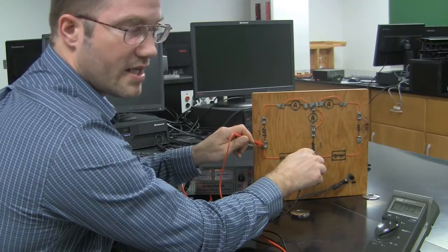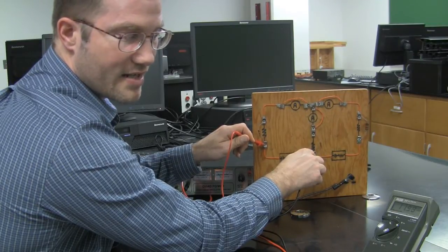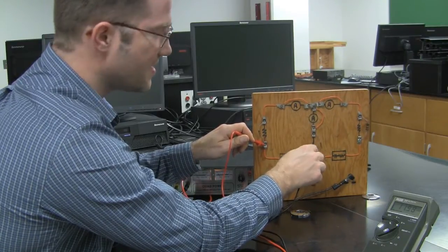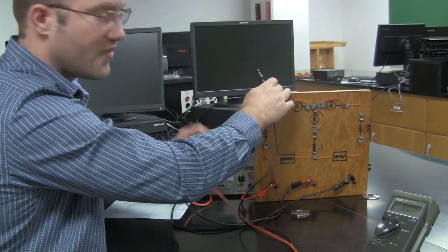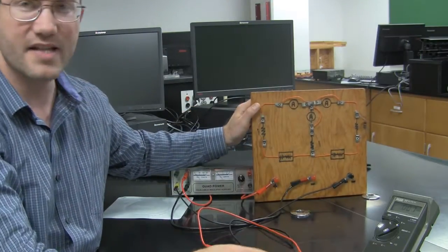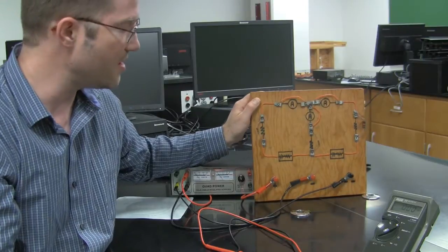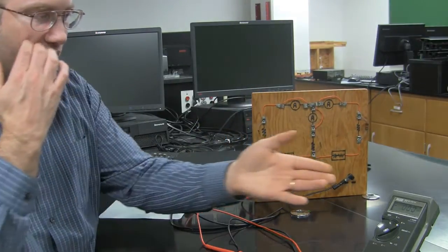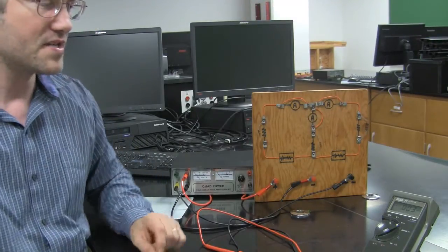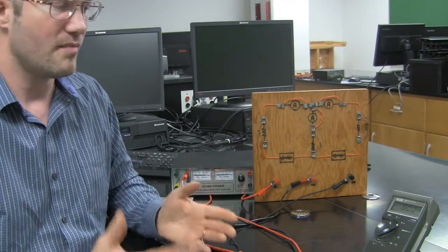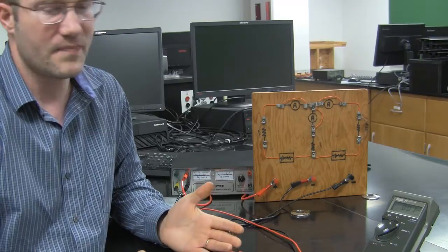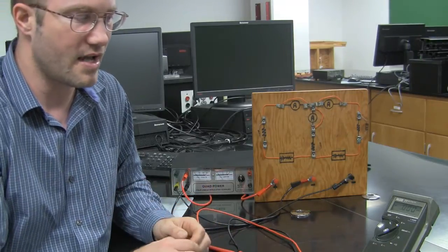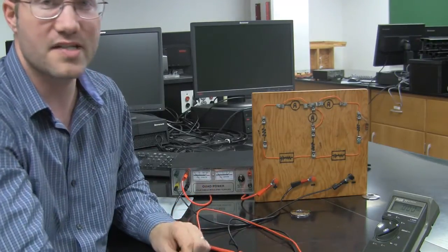And I'm reading 11.99 volts DC, which is actually a lot closer than I thought it would be. I want to write down the exact values of voltages that I read, along with the corresponding uncertainty. So my uncertainty here, this is a digital device, and it's reading 11.99. Well, my uncertainty will just have to be the least count here, which would be 0.01 volts.